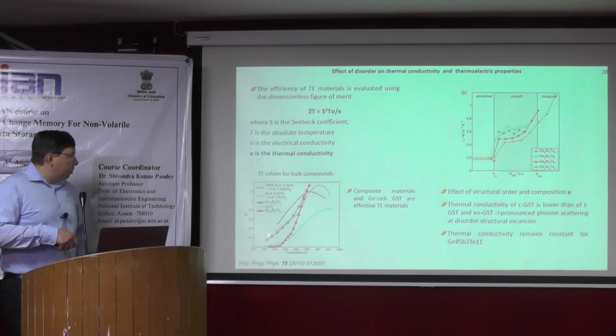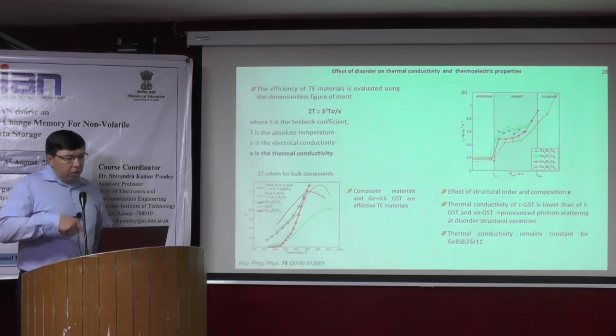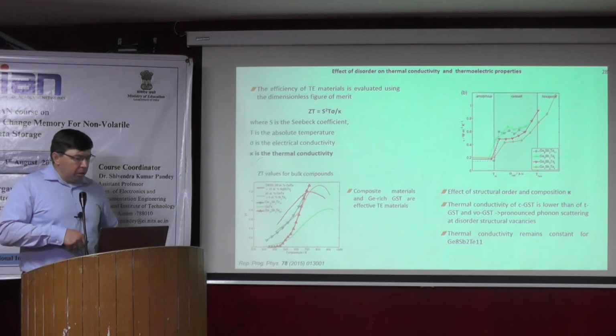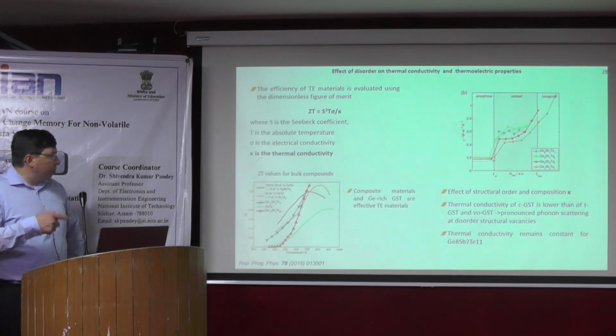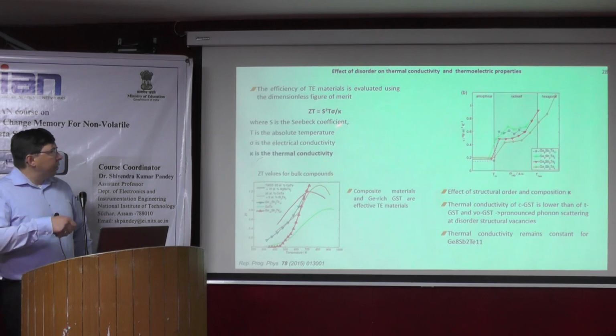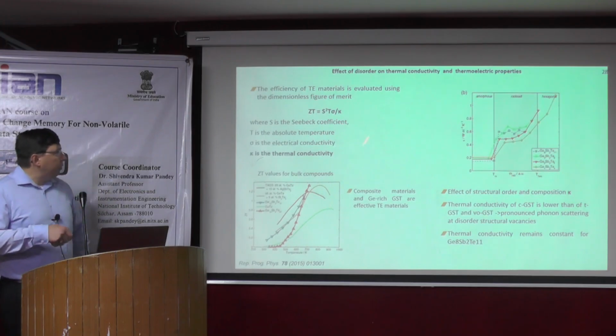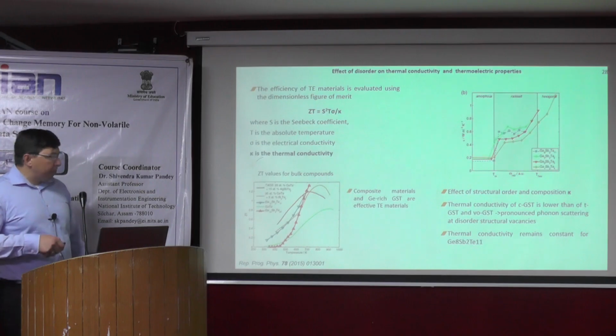Also there was a measurement of the ZT value for GST and for germanium telluride, and you can see that a ZT value of around 1 to 1.2 can be achieved. It's still a low value. We need as high as possible, but it shows you that the material can be applied for thermoelectrics. And so there is also huge research in this direction, on how to improve this, for example, by doping, by mixing, or whatever.